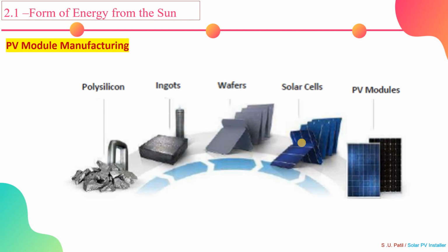Now we will delve into the core material, crystalline silicon, used in the most commercially available PV modules, which is the backbone of the PV module. Crystalline silicon is the preferred choice for PV modules due to its abundance, purity and versatility. As the second most abundant element on the earth, silicon is a readily available source. Its ability to be purified to extremely high levels is crucial for efficient electron transport. By carefully controlling the amount of impurities, we can precisely adjust the silicon resistivity. This property is essential for creating the desired electrical characteristics in a solar cell.